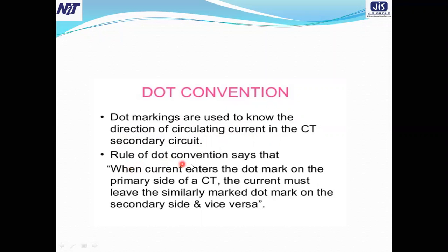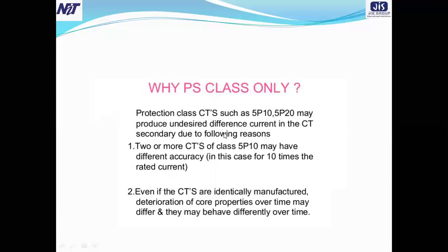Now the rule of dot convention says that when current enters the dot mark on the primary side of the CT, the current must leave the similar dot mark on the secondary side, and vice versa. With the help of this method, we can find out the problem. So this is actually the dot convention of a busbar protection system.